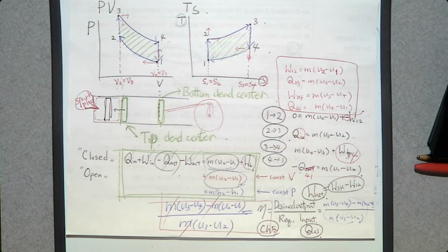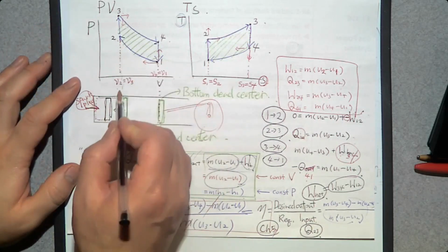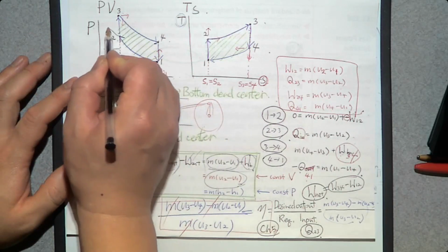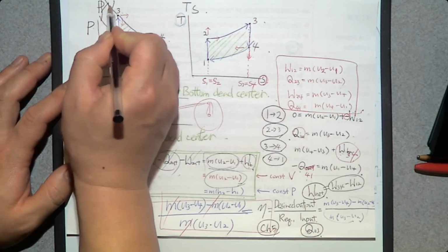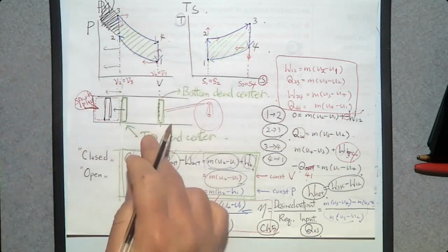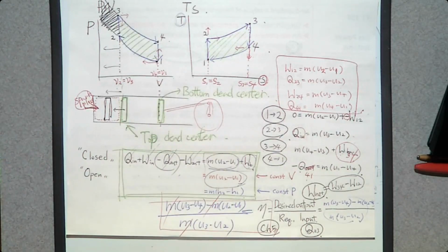So you compress more than this PV diagram. So we are moving to this compression ratio. On this PV diagram, we can add this much work. So increasing the compression ratio is one very significant way to improve the efficiency.